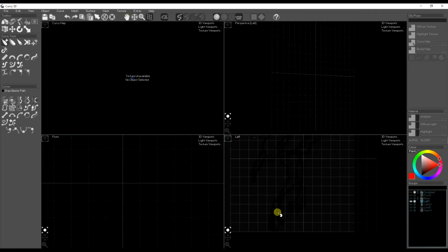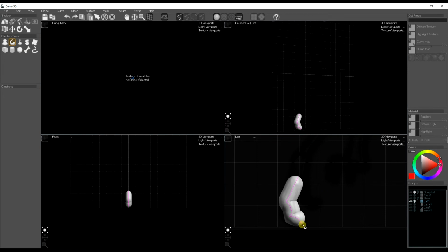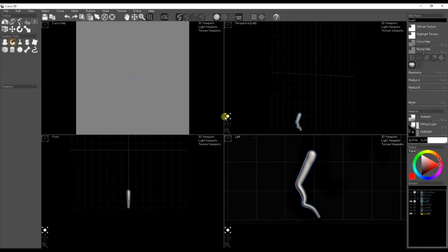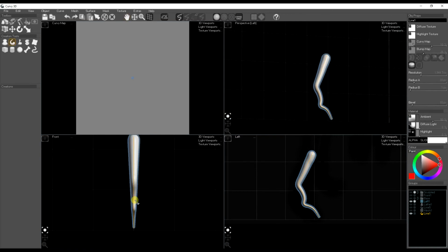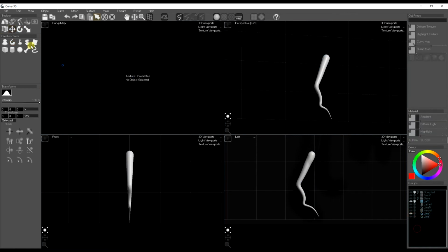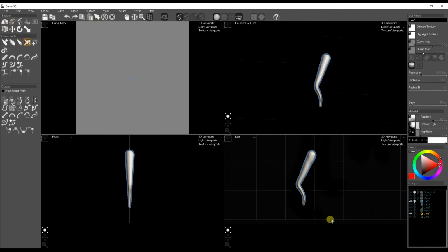So one more part I'd like to show you is where I've drawn his claws and his toes. I've drawn the entire toe with a line object, and once again changing the radius A and B to make it taper off. But then I wanted to split this into two parts, the finger and the claw separately. So I'm going to duplicate this object with Control D, and now I'm going to use the curve scissors tool, trim tool, to cut the object into two halves, or trim each of my duplicates, the finger and the claw